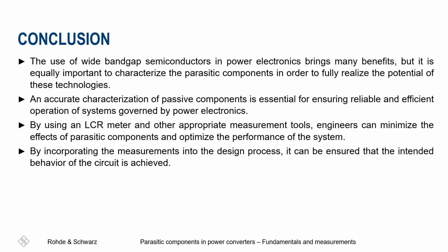Okay, so we've reached the last part of our webinar, and as the main conclusions we could draw of this, it's that in general, the use of wide bandgap semiconductors in power electronics brings many benefits. However, it's equally important to characterize these parasitic components in order to fully realize the potential of these technologies. An accurate characterization of the passive components is essential for ensuring reliable and efficient operations of systems governed by power electronics. By using an LCR meter and other measurement tools, engineers can minimize the effect of parasitic components and optimize the overall performance of the system.